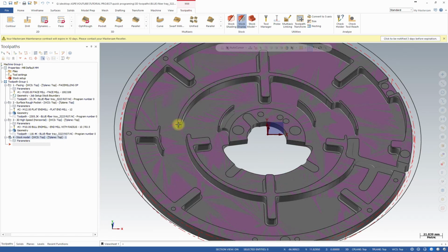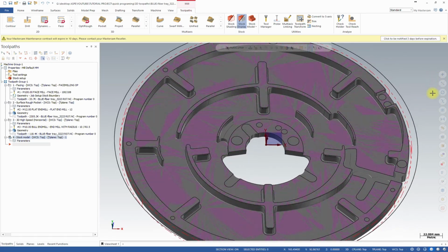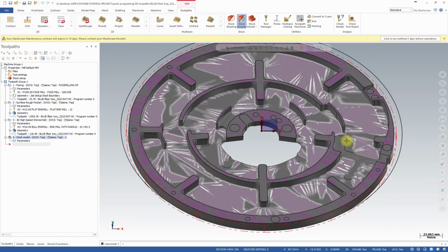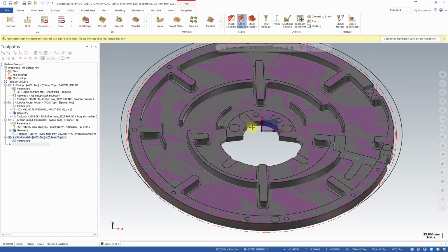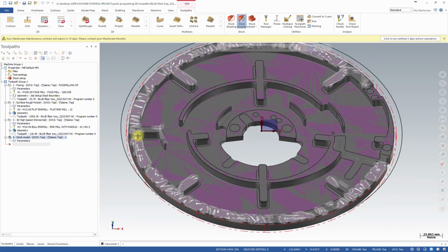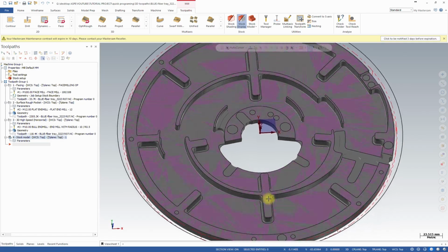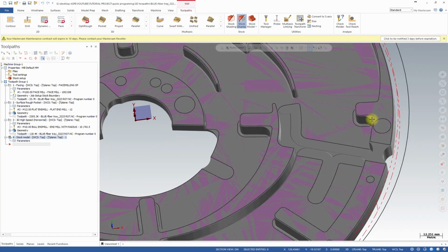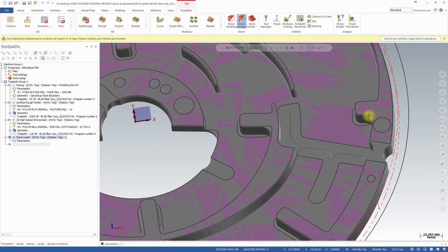Of course, if your toolpath tolerance is going to be tighter, Mastercam will take a little bit more time to generate the stock model. But now we have our stock model, and we can see straight away that we have not even machined this area through, plus these cutouts. Also, we have quite a lot of material in the corners here. Especially with this one angled bit, there is actually quite a bit of material.